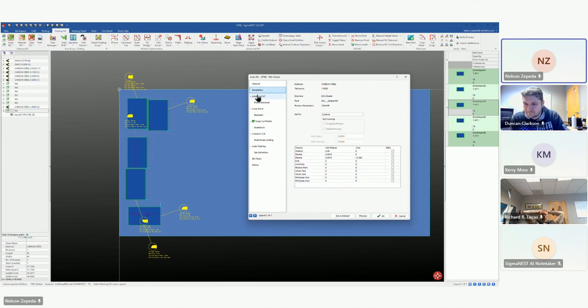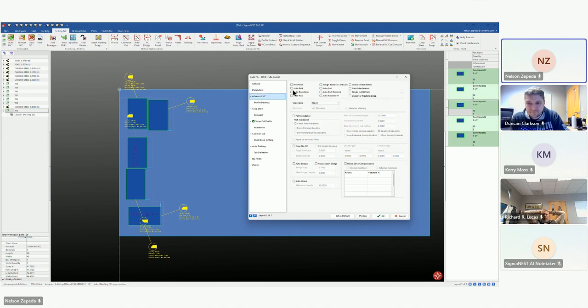There's options in here for auto drilling. I'm not sure if your machine has a drilling head or anything like that, but we can do some auto drilling. There's part avoidance, which controls the rapids of the machine. Some machines, once it starts cutting, can't lift the head up. So in those cases, we can wrap it around parts rather than over them if we need to reduce collisions.